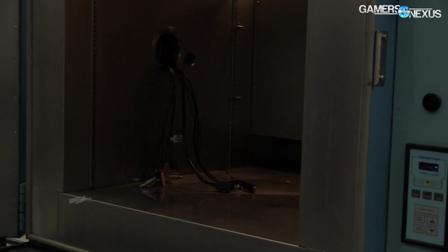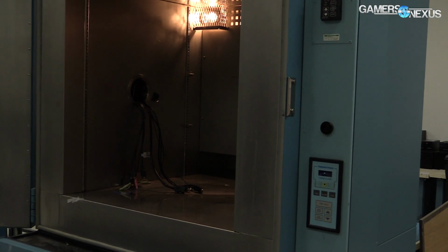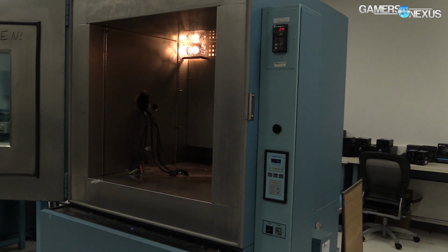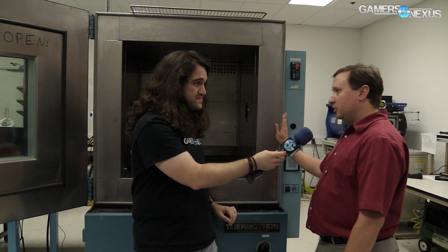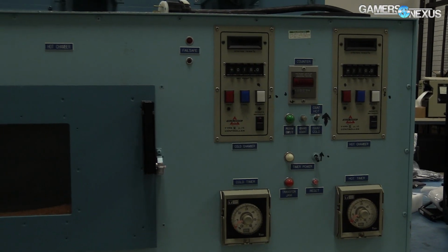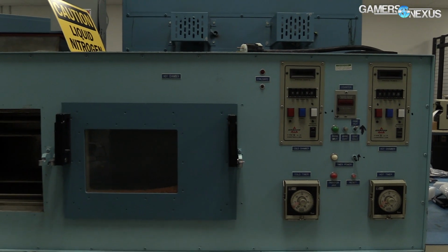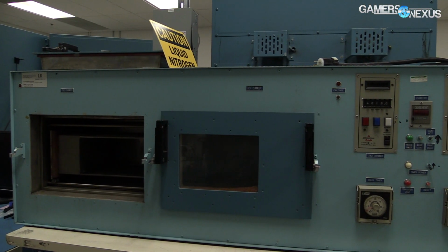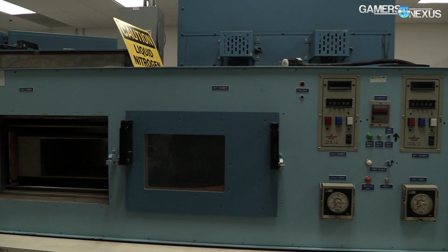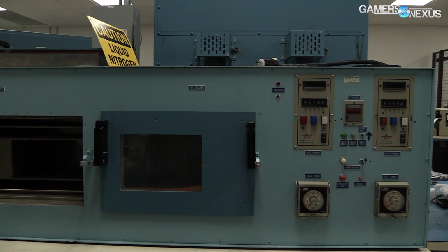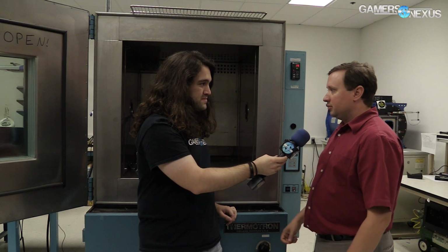So you set the temperature that you want on here, and that can be a high temperature or a low temperature for whatever you're trying to test for, and then it maintains that temperature. Some of them are programmable so that they can go through different temperature ranges. These are basic temperature-only chambers, but they also make humidity control chambers, some chambers with liquid nitrogen for extreme cooling. Some chambers have shock and vibration tables in them for extreme vibration. Some have dry air injection so they can get to extremely low humidities or extreme temperature conditions. But for this industry, temperature only seems to do the job just fine.